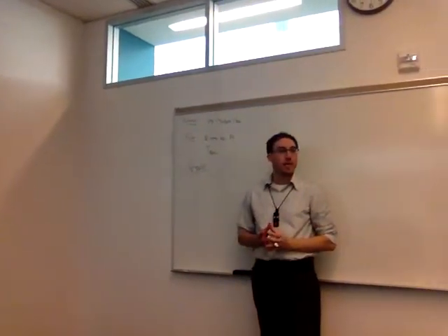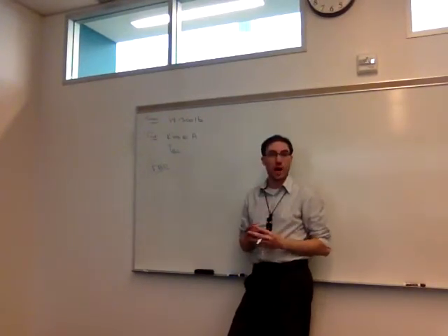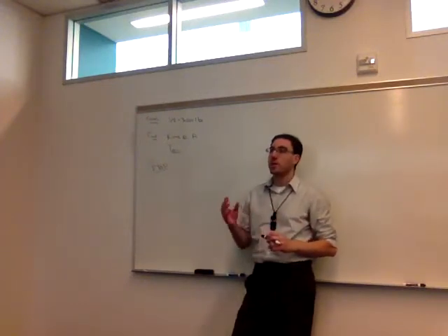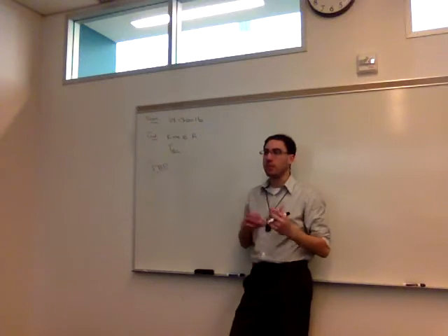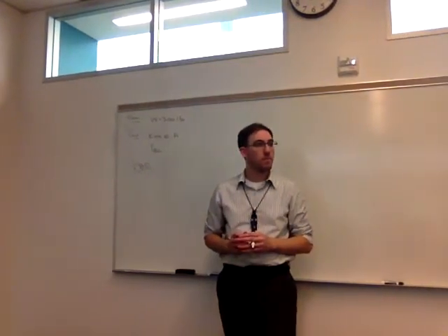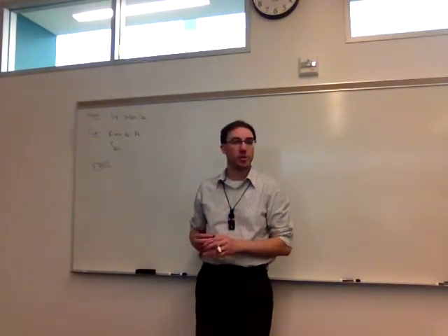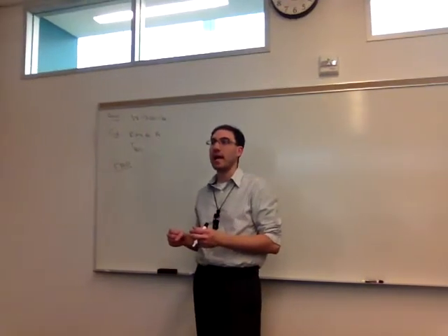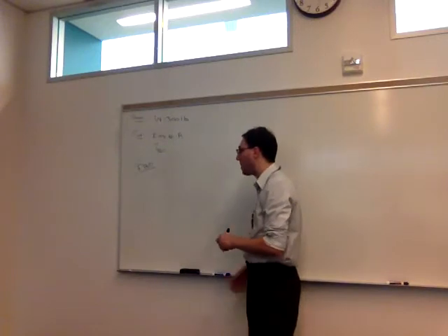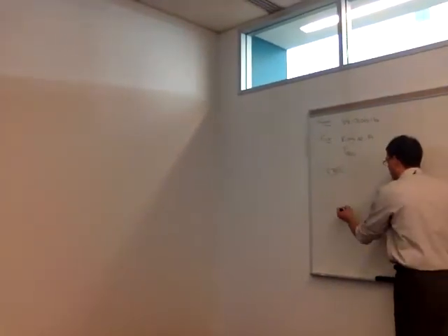So we start with the free body diagram of our situation here. The first thing we have to do is choose what's the object we're isolating from its supports and from all of its other connections. So in this case, what object do we want to take apart from everything it's connected to? Right, so this T-shaped beam, pretty much everything that's blue in the picture here, we're going to disconnect it from the pin at A, cut the rope at D, and cut the rope from B to C, and that will be our object. So we're given a coordinate system here that I'm going to stick with.